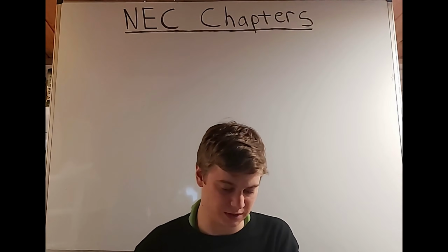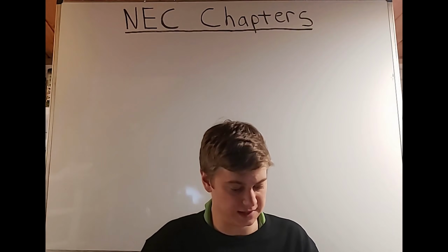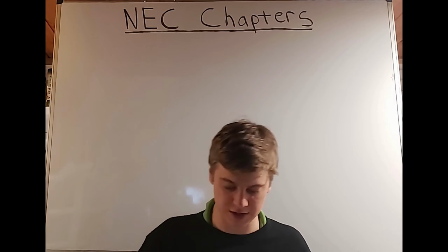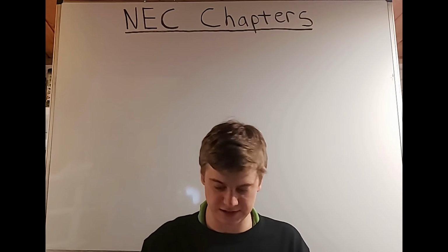That is mentioned in my Chapter 9 video. Then we get into Table 5. You're going to use this to find the size of certain conductors. So you have a number 10 THWN wire. Now you can see the square inches for that.